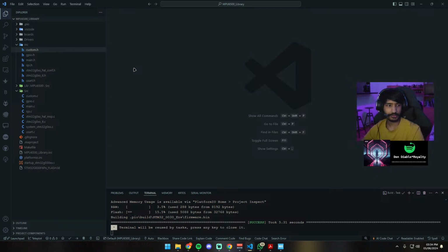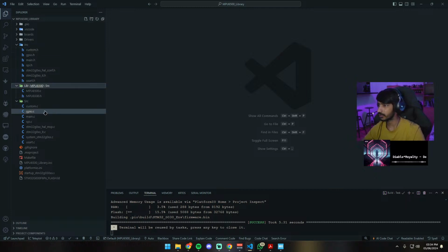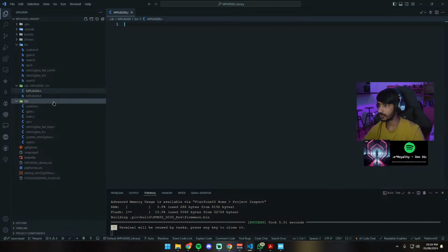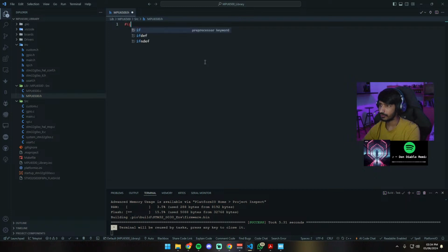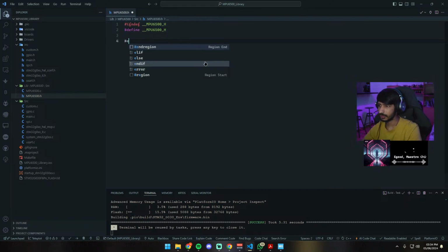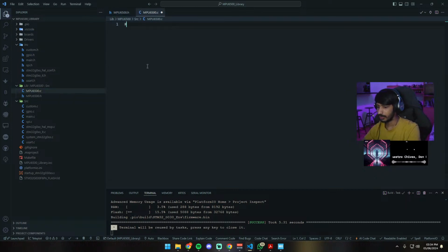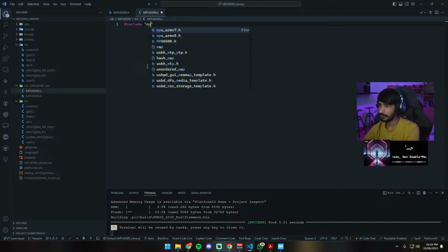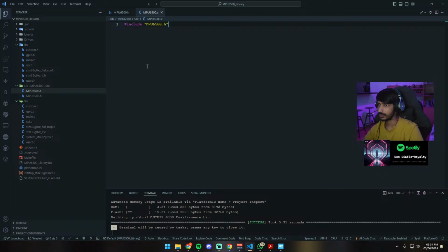Now what are we gonna do? The next step is, we created two files, right? We do the same thing in the header: ifndef MPU6500_H, define MPU6500_H, endif, save, and include MPU6500, right?